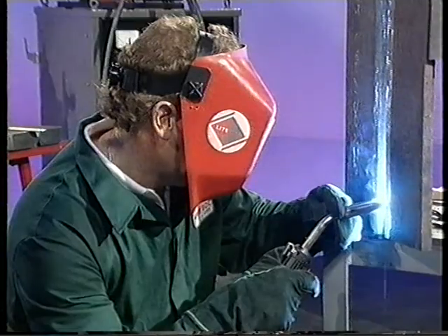And you can hear the weld condition is completely different from that dip that we had before. Hardly any splatter from here. Not too much smoke. A very well controlled weave. Going slowly up the work. Mel was describing, pausing on either side of the bead to make sure enough material reaches its destination.